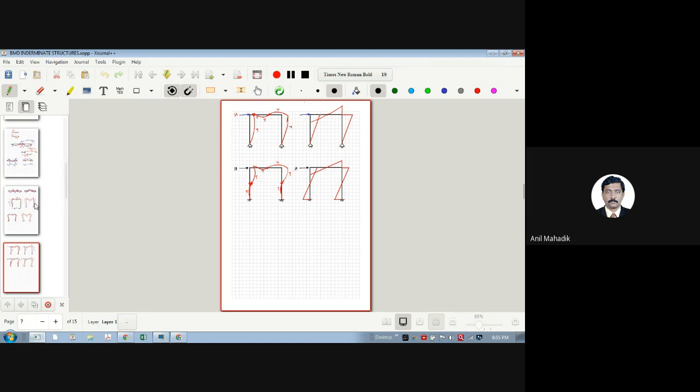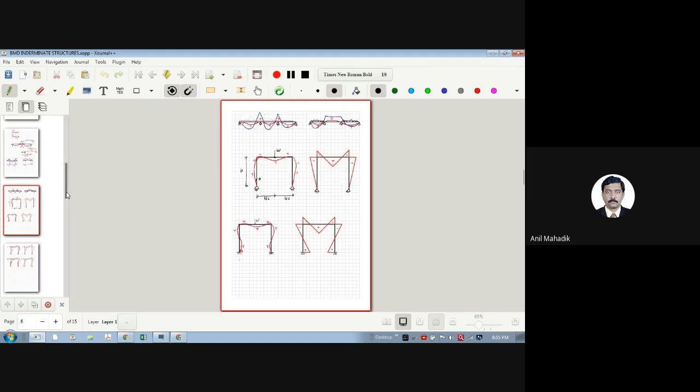So whatever deflection shapes are there, I would say remember that first. But whenever you remember, please observe carefully why it is happening like this, why it is happening like that. Try to understand. I'm not saying you must understand 100%, but try to understand that here it rotates so it happens like this. And if you take some rubber material and put load, will it behave like this? Then try to remember all these shapes for different loading conditions and different supporting conditions first, because this is the basis for multi-story.